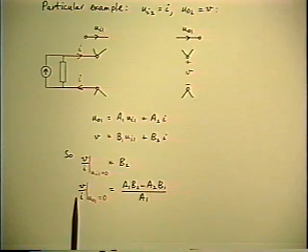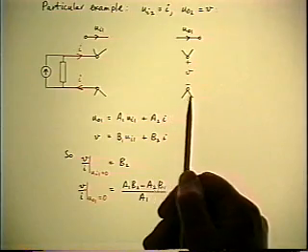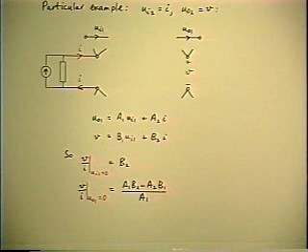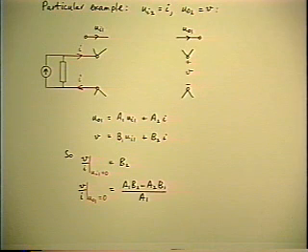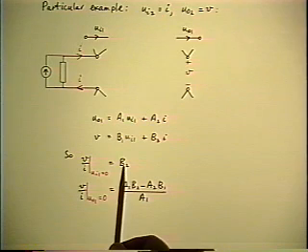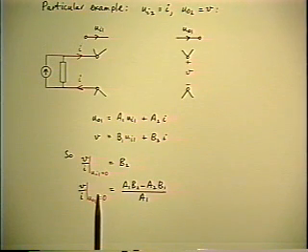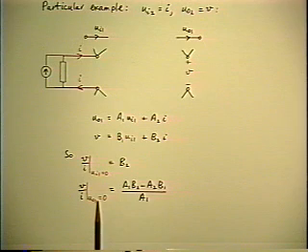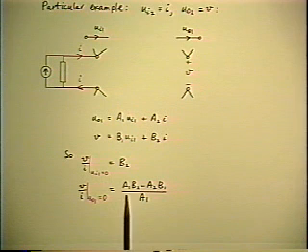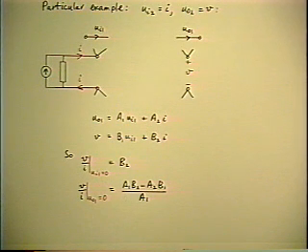The reason you get two different answers is that the V has two contributions, one from each input. Maybe that's an easier way to look at it, in fact. If the other input is 0, you get a unique answer. If the other input is not 0, you can get any other answer, and this is a specific answer when the other input is not 0 and has a specific value, namely the one that nulls the first output. Okay, that's the second time through.